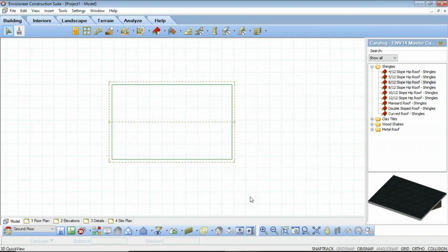Next, I want to add in a truss run. So you can use the truss run tool to quickly insert a run of truss profiles under an existing roof surface. The tool will recognize the hips, valleys, and gable ends of the roof and insert an appropriate profile. It also recognizes any ceiling surface beneath the roof and will alter the profile of the bottom chord to accommodate them. We're going to insert a truss profile run along our gable ends here.